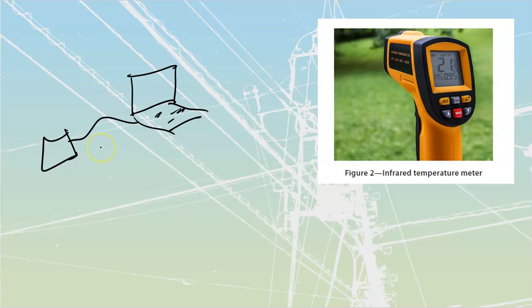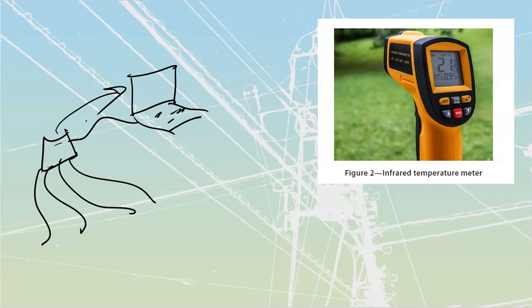It's going to be optically isolated, so you cannot pass any sort of surge along into your laptop, but then you're going to have 4 or 8 channels off of this. They're just going to come into this black box. They're going to be BNC connectors inside of there, and then you just run the manufacturer's program on your laptop. As you run that program, it's just going to read all of this and put it up on a screen. You can make all of your adjustments digitally on that screen.